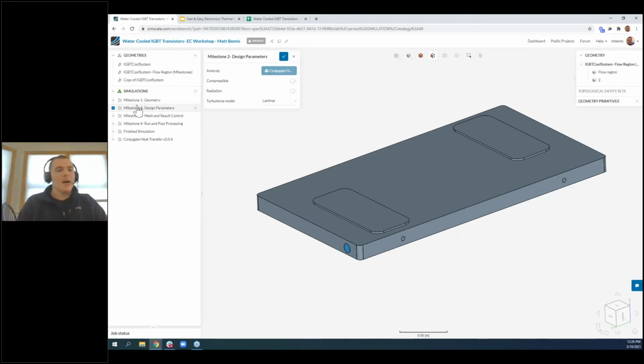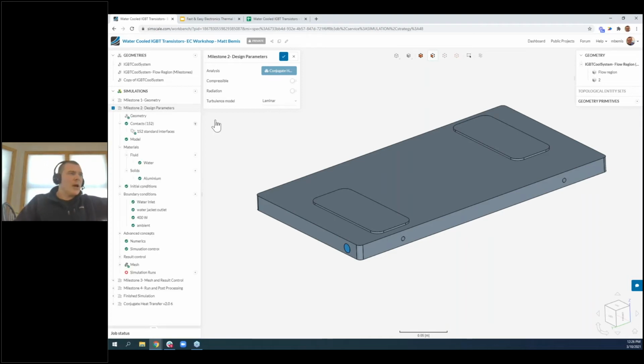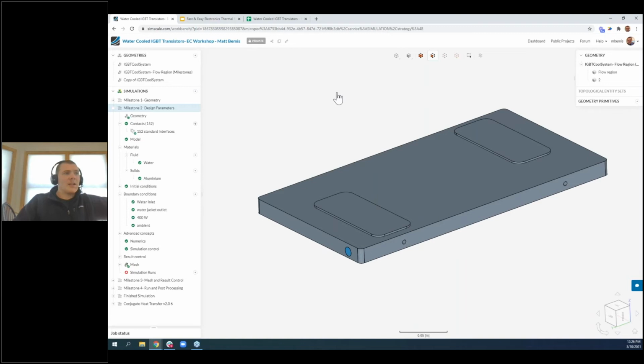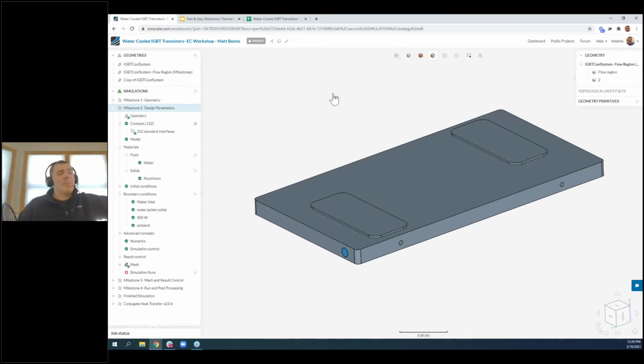Sure. That's a very good question. With simulation, you tend to really just want to take the worst case. So here, steady state with both IGBTs turned on at 400 watts continuous, that's the problem we're solving for, and we'll understand what that performance is. If that performance is acceptable, we know we can really handle any kind of transient behavior.